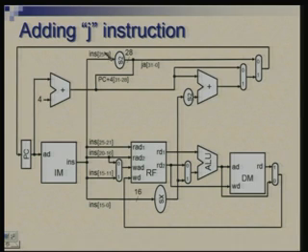We are taking these 26 bits from the instruction field, shifting them left by 2 positions to get 28, again for the same reason, we want to get a byte number from the word number. 4 bits we are picking from PC plus 4, bit numbers 28 to 31, and these 4 bits and these 28 bits are concatenated together to form a jump address, which is a 32-bit value, and this is available as yet another input for going back to the program counter.